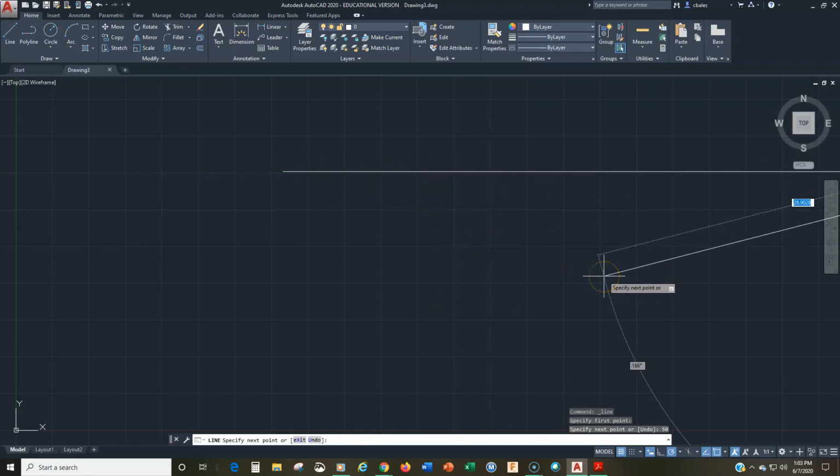And whoa, look at that. It shoots way off the screen there. Let me just end the command. So what's going on here? Well, remember that I started with the ACAD template, not ACAD ISO. This template was set up basically zoomed in too far. It was zoomed in for an inch drawing where you're drawing not 50, but 5 for 5 inches, not 50 millimeters. Not 50 units, but 5 units.